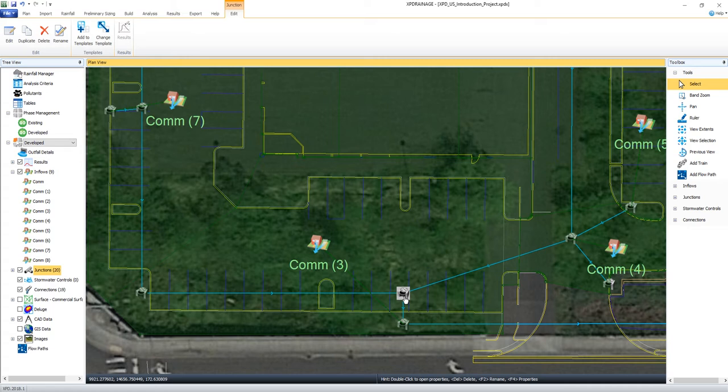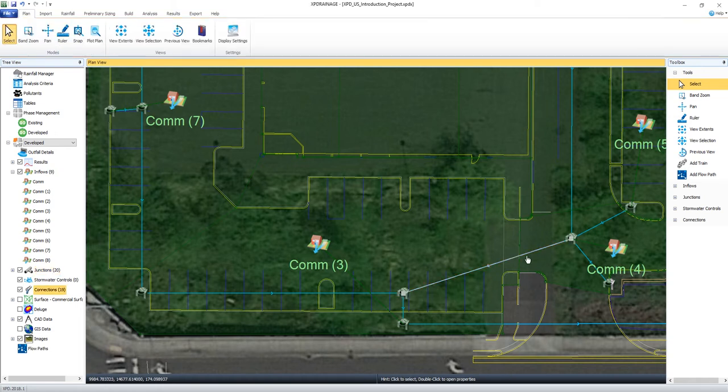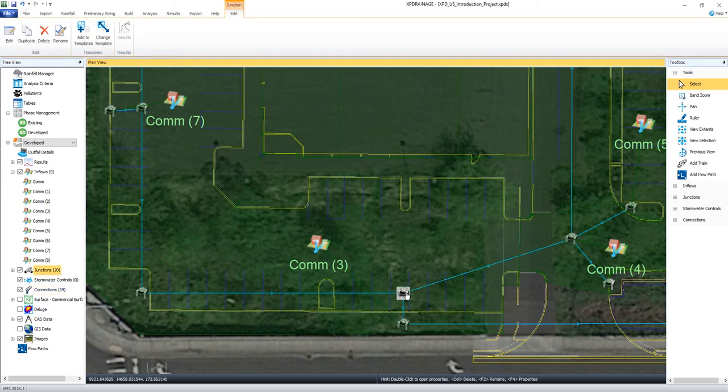So often when working in CAD or working in GIS, these can be limited systems when trying to represent and assess stormwater designs. So in most systems like CAD, when we begin to lay out a pipe network and a stormwater treatment train, there aren't any outlines, as we'll see we can use in XPDrainage, to guide our assessment. So those tools are limited to only using links, right? These lines, we're going to call connections, or these nodes are points. So in CAD, what really is supposed to be an underground detention system is represented simply by this one dummy